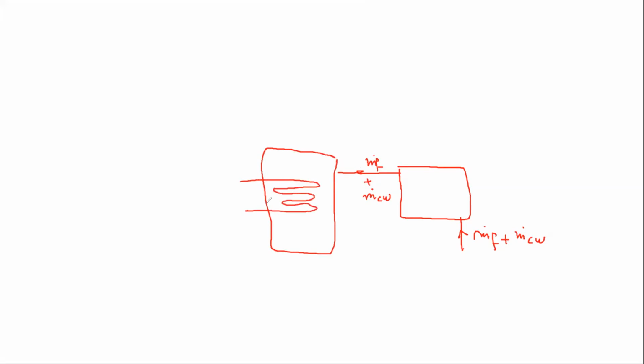It will be a lot of steam, which is going to generate a lot of vapor. When this vapor comes in, this quantity will not be enough to condense it all. So always you are going to need more water in, just to make sure that you condense all the vapor that is formed here into sweet water. And then definitely you'll have to throw something away. I hope I answered your question this way.